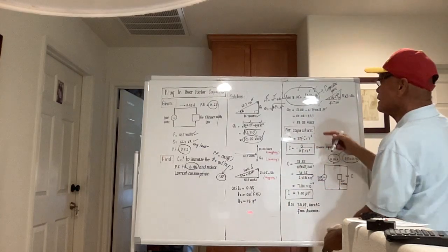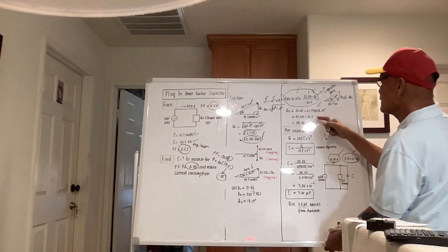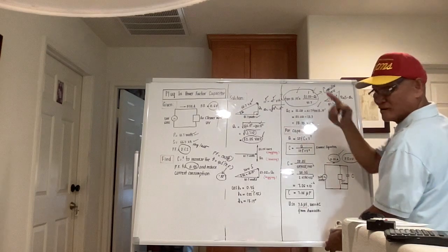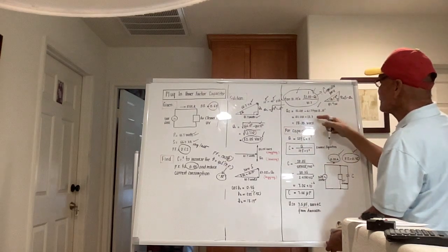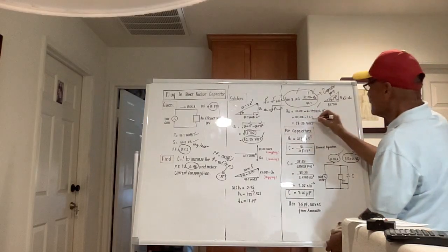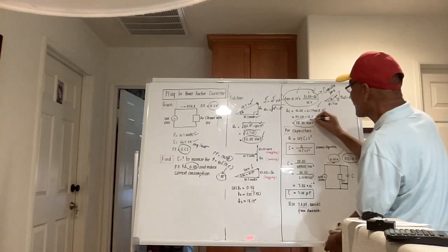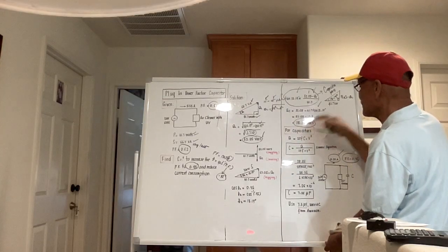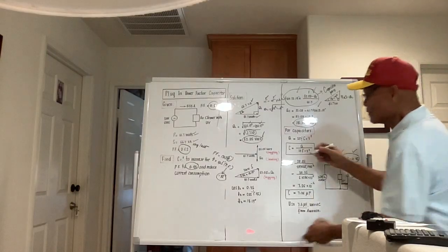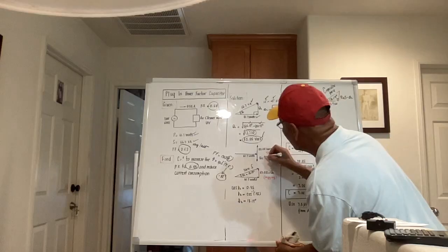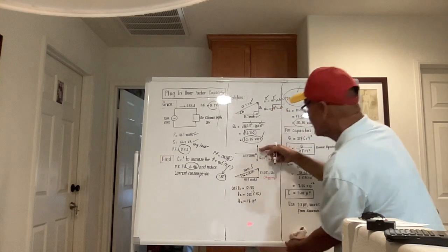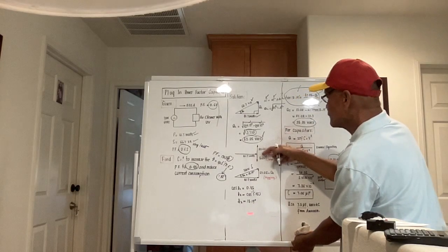Algebraic manipulation. So this will be 52.05 minus, if we try to compute for this one, the tangent of 18.19, that's less than 0.5, times 41.7, that's 13.7. So 52.05 minus 13.7, the reactive power of the required capacitor is 38.35 vars. Okay, 38.35. This portion here is 38.35. The downward, this is 52.05.